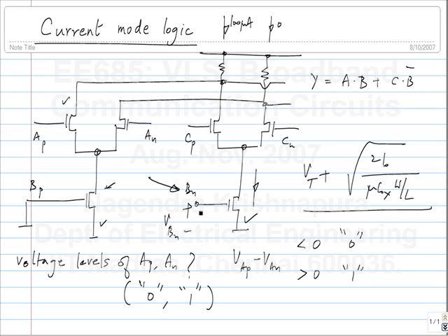Now the current is directly dependent on this. It goes through square law if the transistor is obeying square law. And so, the output swings will change depending on VBN. That is certainly not something you want, because then driving the next stage may become difficult. If the current becomes too low, it may not switch it. What happens if the current is very large? You are saying there is only a lower limit, not an upper limit, right? Yeah, so it is definitely there.